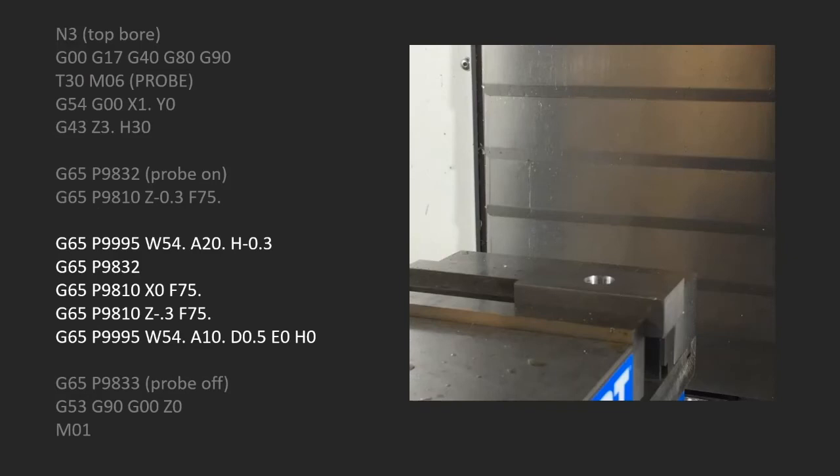So now this is another example, and this is using the 9995, the conversational version, and you see that once we probe our Z, then we have to turn the probe back on to do some safe positioning, and then our final probing, which is to find the center of that hole. So here's what that looks like.